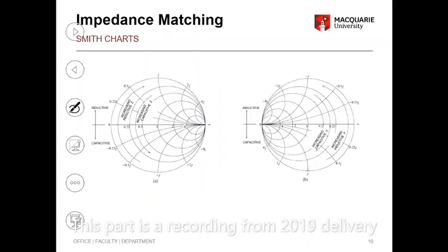Now, a few things that we need to remember here. This is a very important slide. It will actually tell you how to design your matching circuit. Because you wouldn't know whether to have an L and C, whether to have a C and L, whether to have LCL. You don't know that when you have a circuit. So what I want to get out of the lecture at the end of the day is that when you have a source and a load, you will know what the circuit looks like, not the values, but whether it's an L and a C, whether it's a C and L.